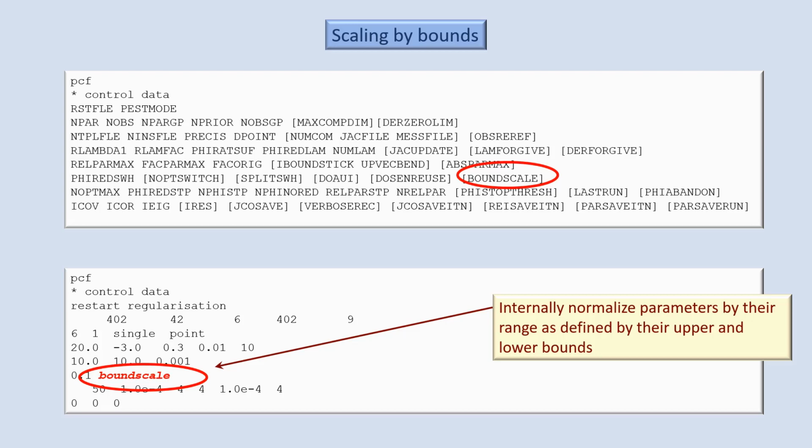That is, they are all scaled by their prior variance, their prior standard deviation. Now, we don't do that with PEST because we don't provide the prior probability distribution of all parameters to PEST. That would be a little cumbersome and probably a little subjective. Nevertheless, sometimes if an attempt is made to do this scaling, PEST can perform better.